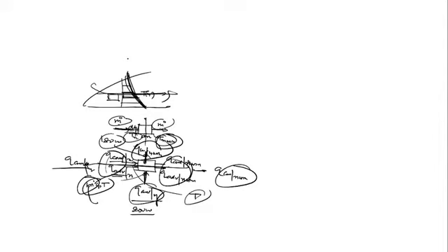because in the energy balance there is advective flow involved, and advective flow involves the flow rate, that is, the velocity distribution. My dear student, you are never supposed to solve the temperature distribution without knowing the velocity distribution. It means we must know the energy balance as well as the momentum balance. Both are required.